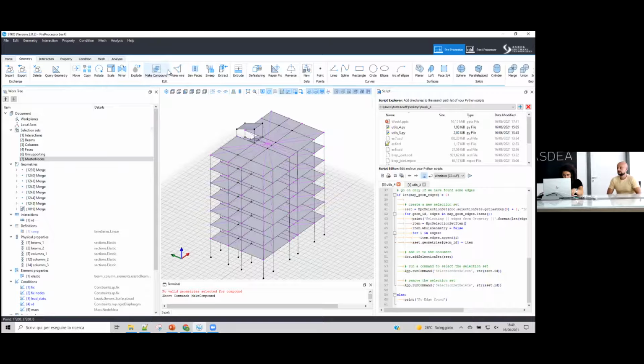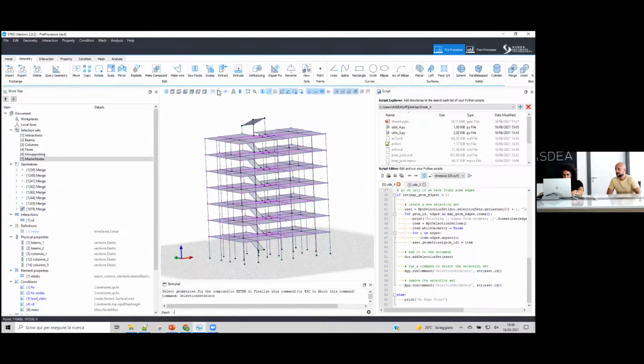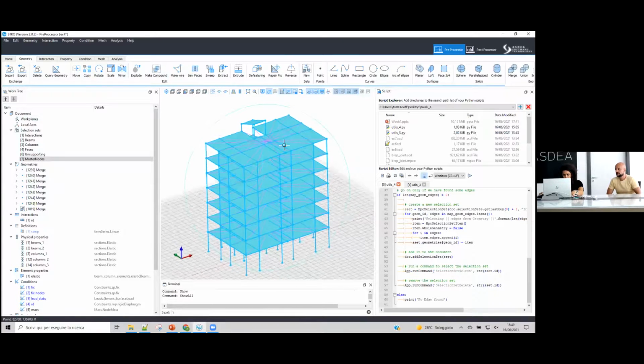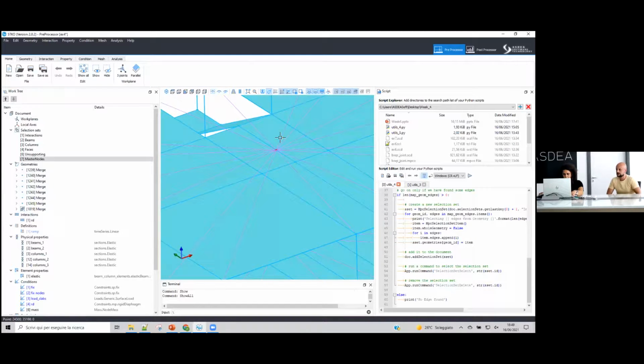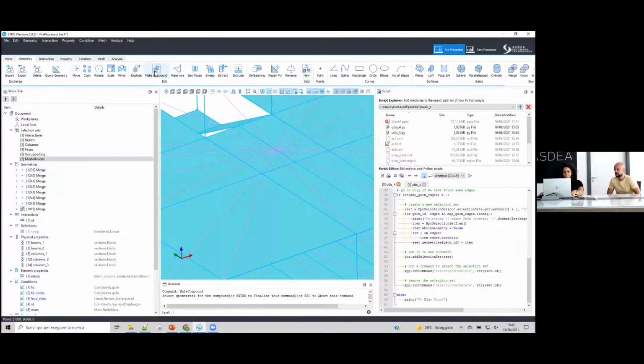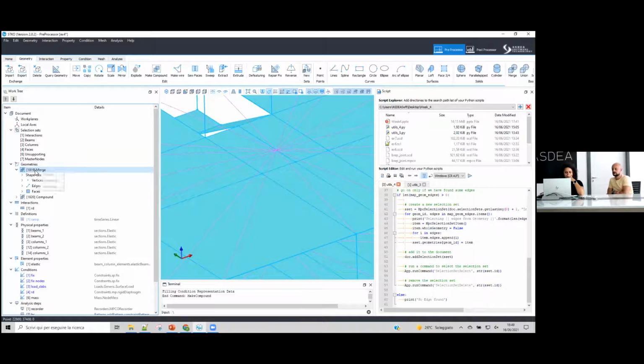Make a compound, select your master nodes. Maybe they're not showing. When you select them, let's go back. In selection set, you're selecting the sub-geometries. You can select them from the geometry. For example, there, you select all the geometries. Select all of them, make compound. There it is. Okay, so you can rename it, for example, master nodes.